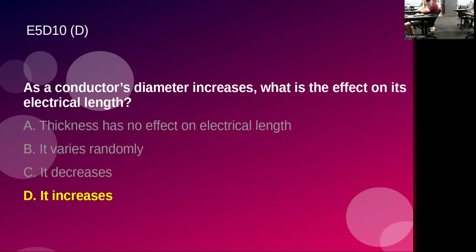And so that's why I thought increases, because you've got a bigger conductor, like RG-8 versus RG-58 or something like that. You're basically saying you're getting more power at the other end. Well, the basic difference with those coaxes is the physical size is larger, you have less loss. Right. So this almost follows.